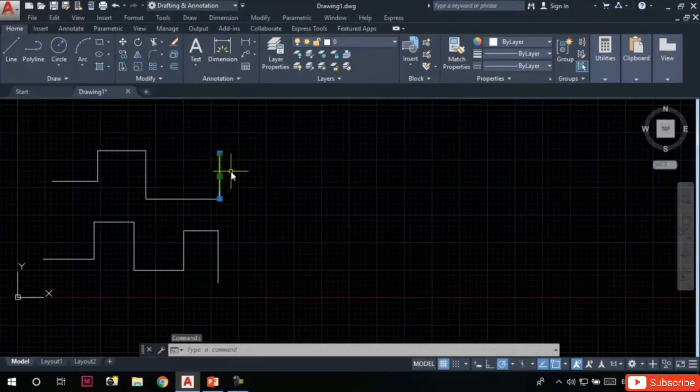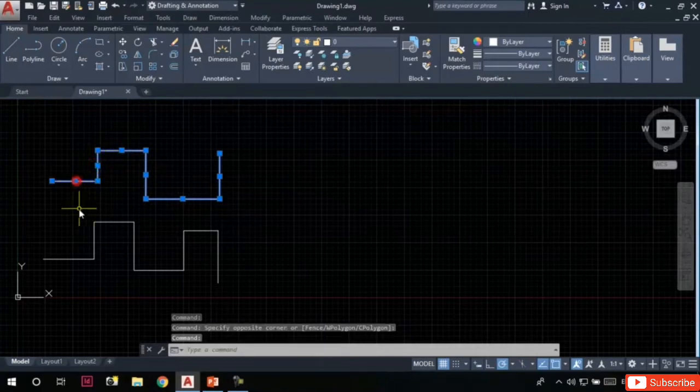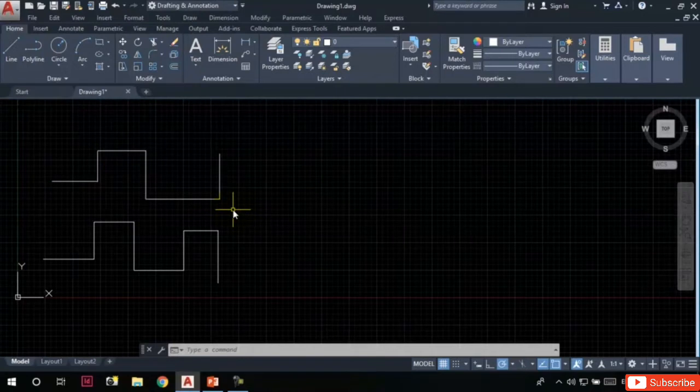This line segment will be selected separately, and to select the entire sketch, we need to select each and every line segment separately. So the sketches drawn using the line tool are not a single entity. They are a series of line segments connected together. We can also select this sketch at once, but for that we need to know about the window selection methods, and we'll discuss them in upcoming sessions.